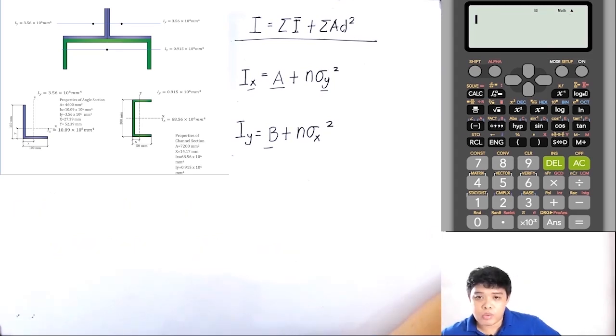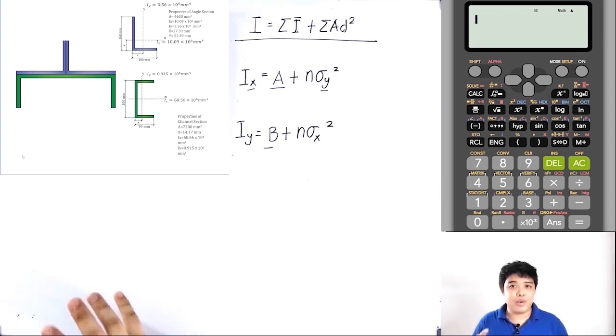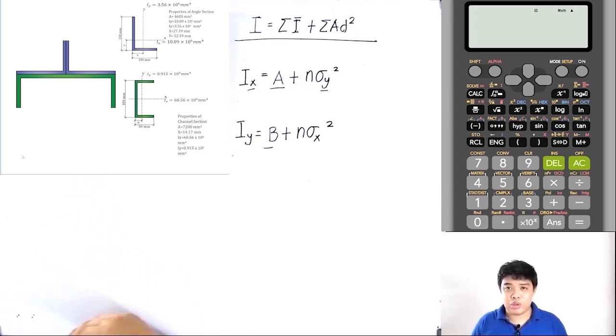Before you go to start mode, let us recall the section properties. At first, we don't know where the location of the centroid of this figure is. If you are getting the centroidal moment of inertia about x and y of the whole built-up section, you should have an initial origin first. You have to establish your initial reference line parallel to the x and y direction. So what is my tip? If your section has an axis of symmetry, you can use it as your initial reference line.